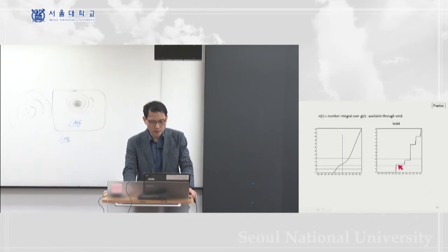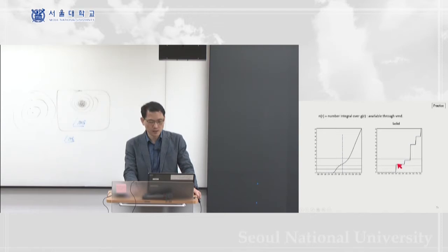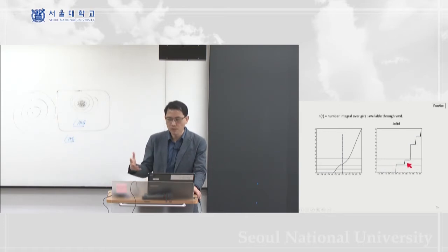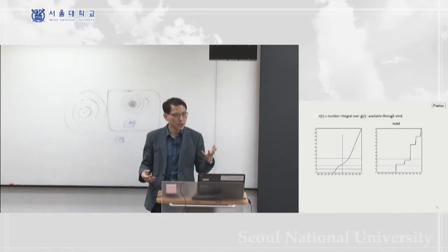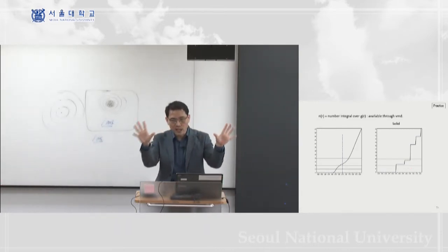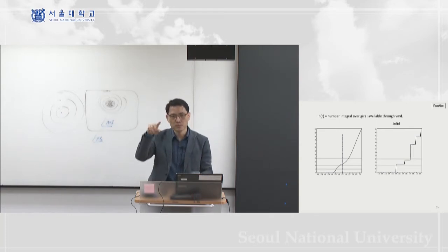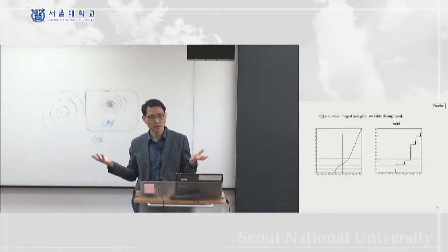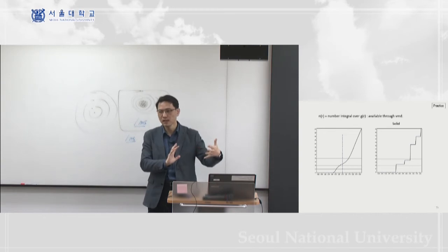You can compare this with the solid phase. In the solid, of course, it's an FCC aluminum structure, and therefore in the first shell you have the 12 nearest neighbor atoms, right? Again, it is exactly given by this figure here. So you have a similar number of atoms in the liquid phase. This is typical. In the liquid phase, even though it is a dynamic and also disordered system, its first shell is pretty much similar to the solid phase. Similar coordination number, and also similar bonding distance.